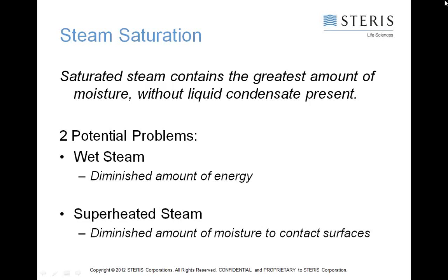Now, drying is typically the last part of the sterilization cycle, and usually it occurs as a vacuum is drawn. Since when we draw a vacuum in the autoclave, or anytime you're under a vacuum, the boiling temperature of water decreases. So it takes less energy, less heat for that water to boil and evaporate. So we pull the vacuum, and then the amount of heat that is contained in the items being sterilized itself kind of provides that source of heat to